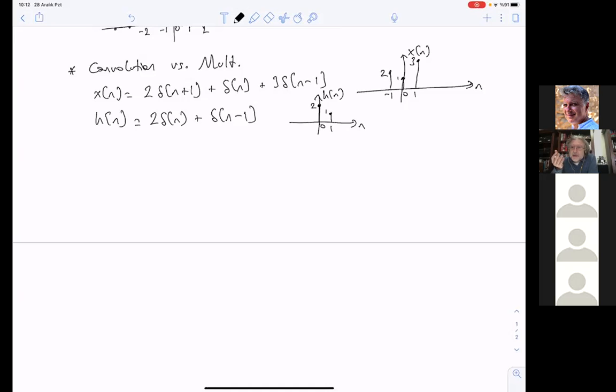Do you know how to perform the convolution? You fold around one of them. It could be h of n or x of n. You fold and then slide over the other one. And the corresponding locations are value-wise multiplied and summed up, accumulated. That's the cumbersome operation of convolution.